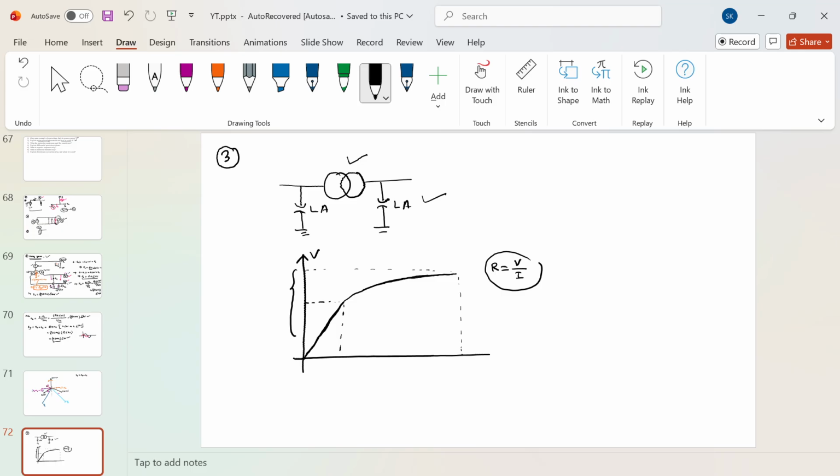For the protection of the transformer from internal faults, because inside the transformer there can also be various types of fault that we call internal faults, we basically use the Buchholz relay. So this is our lightning arrester, then we have the Buchholz relay. We use it inside the transformer to detect internal abnormality of the transformer.